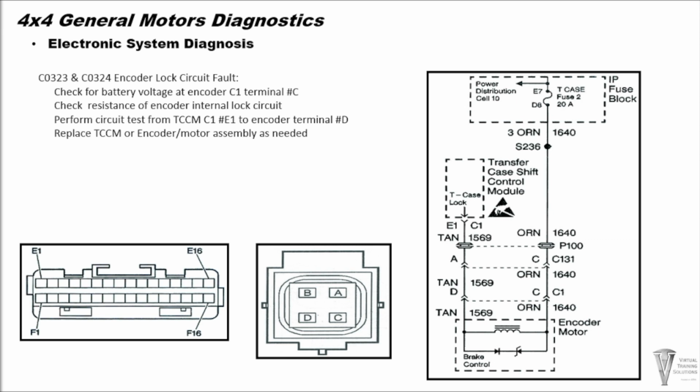If the resistance is not within specifications, replace the encoder motor assembly. If the lock resistance is within specifications, a circuit test of the lock circuit would be recommended.